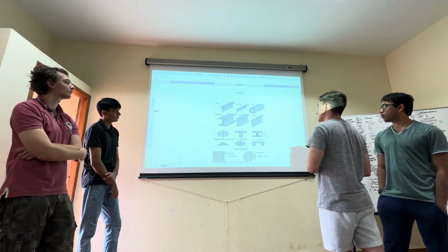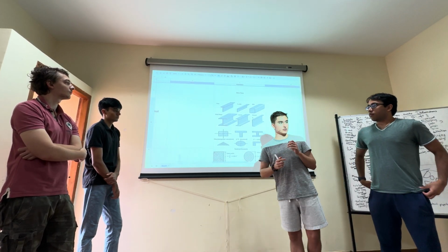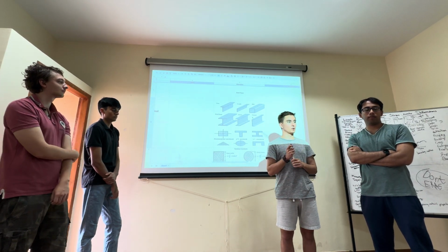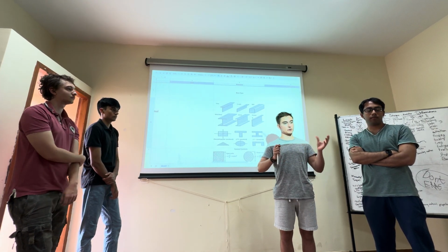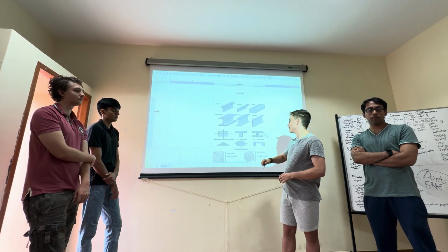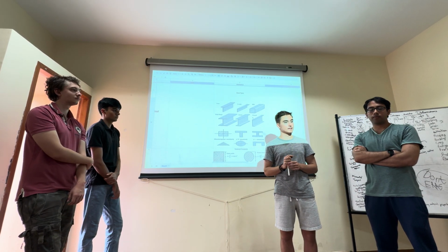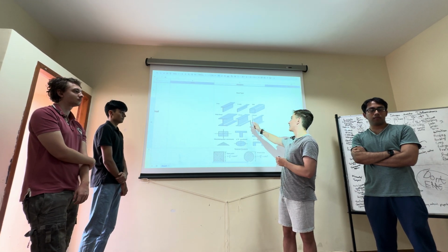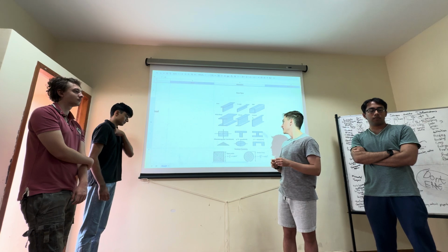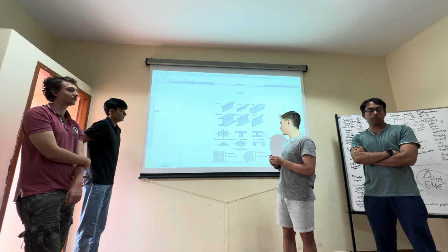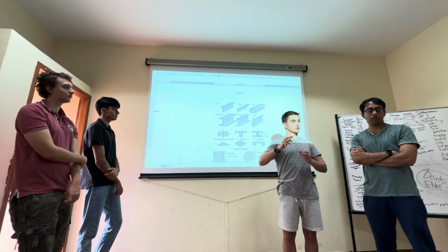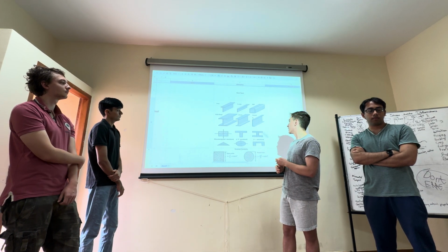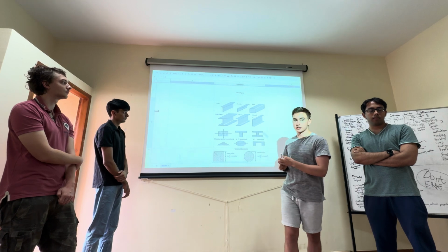So with different beam types, and we didn't go into this as much in this class since this would be more of a civil engineering application, it's still at the core of structural analysis, and what we elaborate on within beam types is also important within aerospace applications. But with different beams, like the classic I-beam or the flange or the T-bar, they're going to have different moments of inertia that we can find based on their shape. And so that's the core thing that we wanted to elaborate on, where depending on what sort of shape you had,